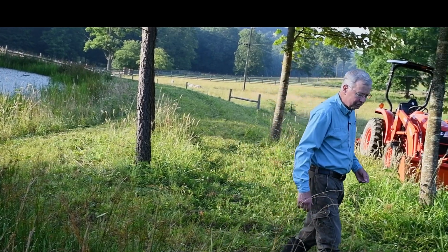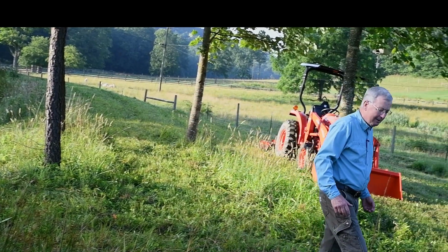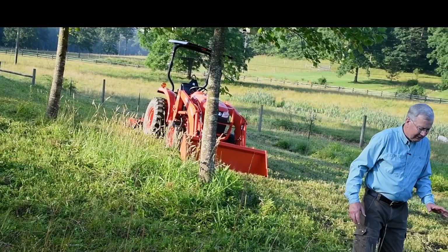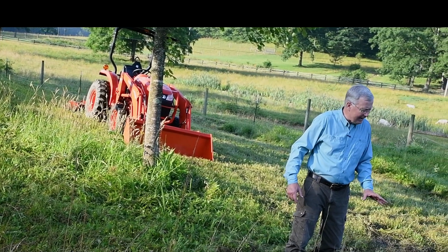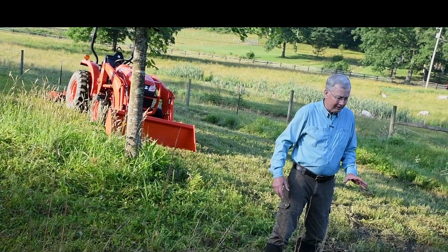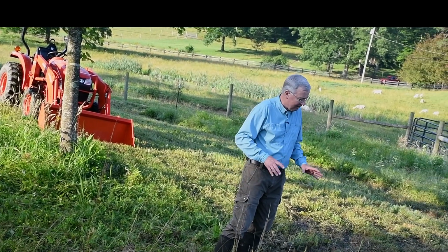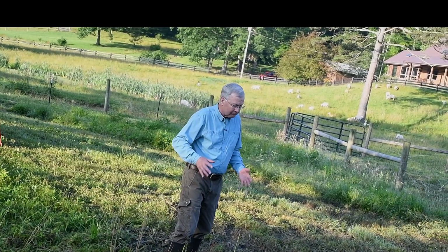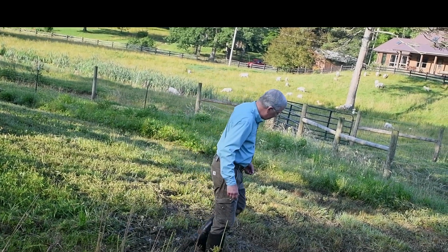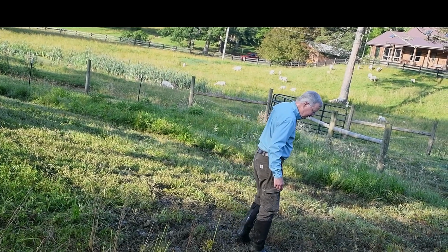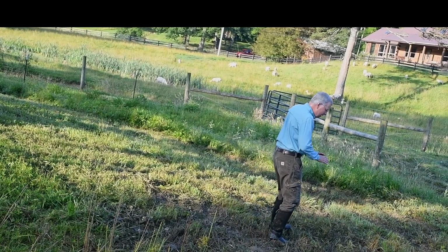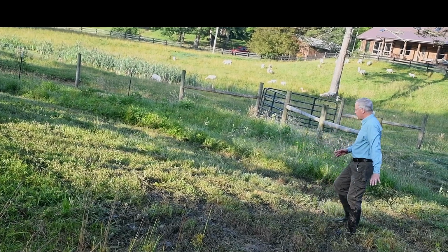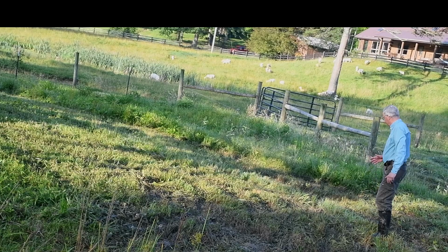and it looks like the water is just seeping out of the wetland and not causing erosion. But as I come over here, there are some ruts that I just caused when I mowed the dam. I was going through the spillway, and because the soil was saturated, I left some ruts behind, but they are perpendicular to the flow, so they're not causing any problems. And again, I'm walking the length of the spillway now. The water is still spreading out and not causing any erosion.